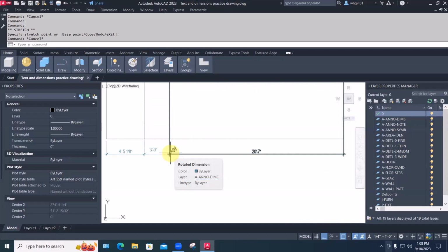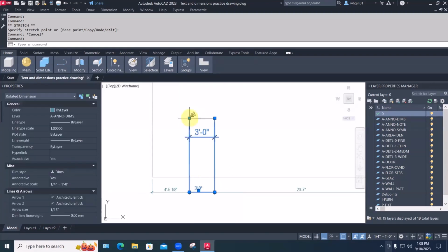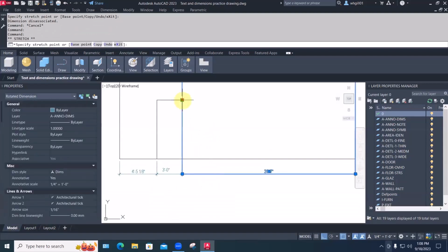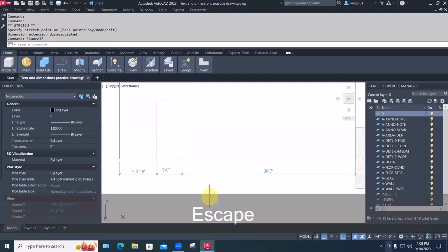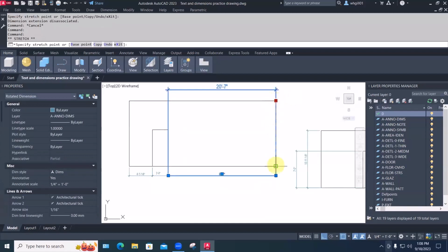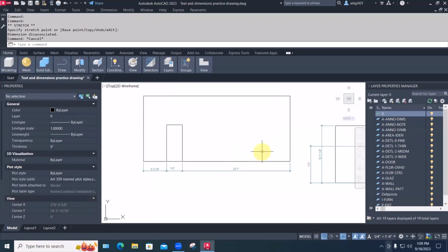And what I just did obscures that a little bit because my dimension lines themselves still go clear to the top. So I think what I do here is pick this one and tell it don't dimension from that point up there, dimension down to this point down here. And we'll do the same thing there and there. Partially fixed. And now this one is still going all the way up, so I'll pick it, drag down and snap to there. And I'll do it over here as well. So now they're all nicely in a row. You can see they don't overlap. I got a consistent line all the way across.